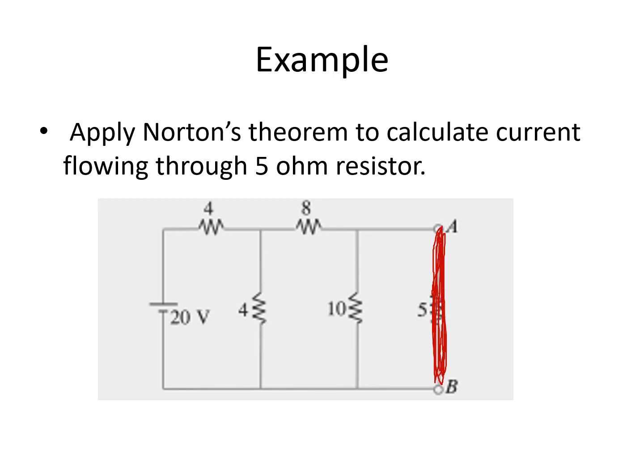If this is short circuit, this will also be bypassed, because if you are the current flowing to this junction, you want to pass through here and not through the branch with a resistor. Therefore, 10 ohms here will be bypassed. So by removing the 5 ohms and replacing it with a short circuit, 10 ohms is also short-circuited. So we now get the equivalent resistance.